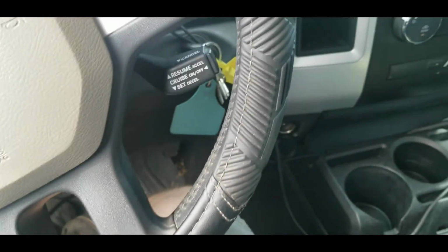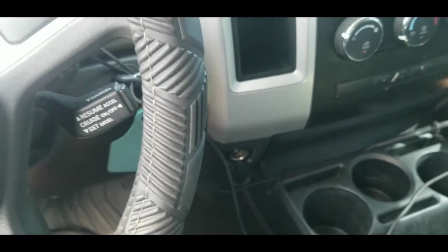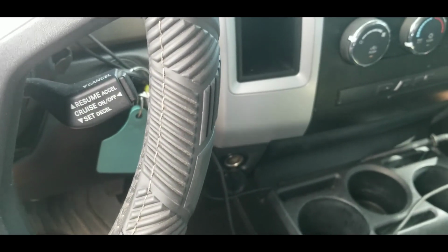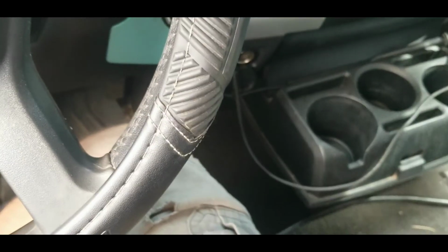comes back on, which leads me back to believe that there's an internal fluid passageway that when the 2C clutch turns on to fill that clutch, it turns on the clutch to turn on second gear. It starts to turn on second gear, but then there's fluid passage and it starts to build, which is where you feel the drag. It starts turning on another clutch, it feels like. And then you get that closure of that 4C pressure switch. And that 4C pressure switch isn't supposed to come on while the other clutch is on. It's supposed to turn off that clutch.